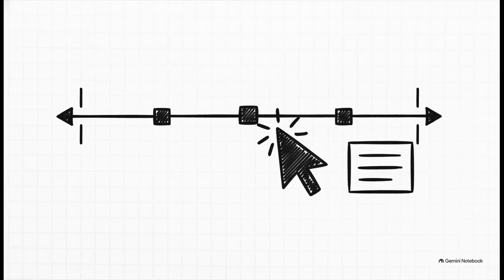You literally just click the dimension to select it and use those little highlighted grips to effortlessly reposition the text or extension lines. Need deeper control? Just right-click and pull up the full Properties menu. But hold on, just like with our text notes, individually tweaking grips and properties manually for every single dimension on a massive floor plan? Yeah, no way. That's incredibly inefficient. Which brings us to our final macro-level tool.